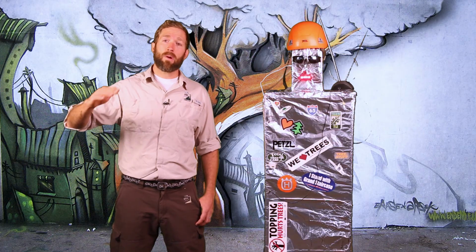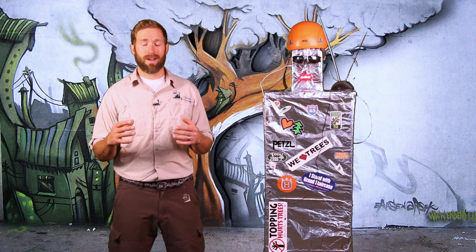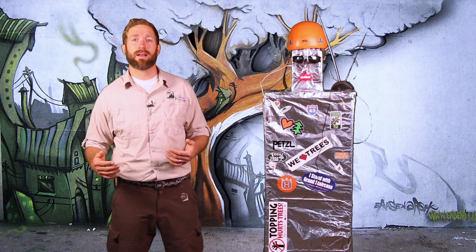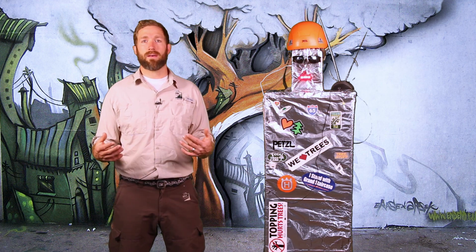All right, so there's one very important point that needs to be made in closing. The installation of tree support systems or lightning protection systems represents an ongoing responsibility to the arborist. Basically, any time that these are installed, we need to explain to the clients that a periodic inspection needs to be done. If any faults or changes have happened when we inspect these, then we need to go back and repair and revamp our system, okay?